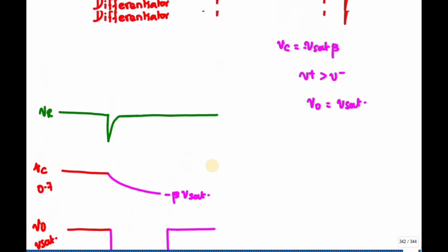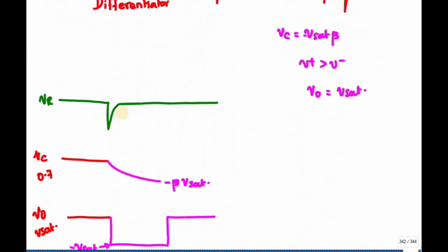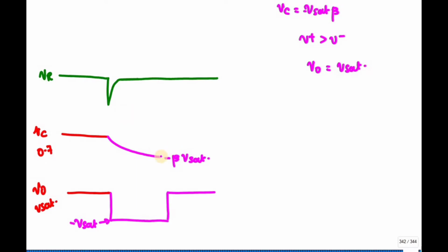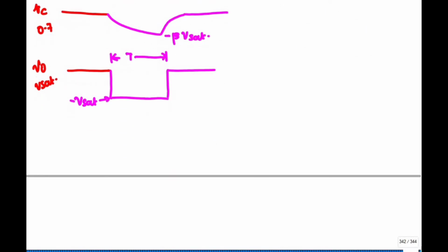And the capacitance starts to charge, right? So the capacitance starts to charge and it will again reach the value of 0.7 volt. Okay. So which one is the time period? So this is my time period, right? So now I can write what is Vc of t.